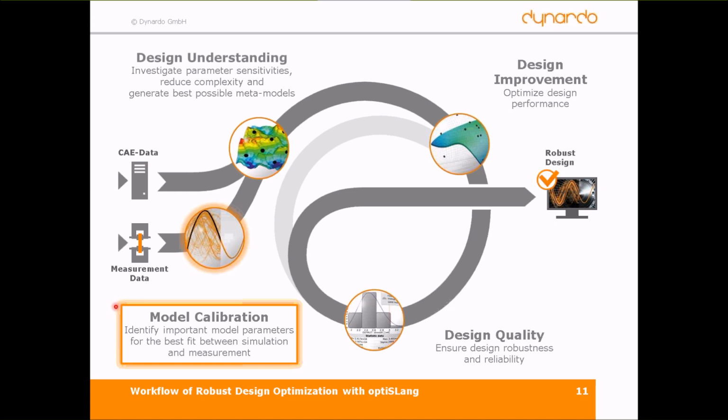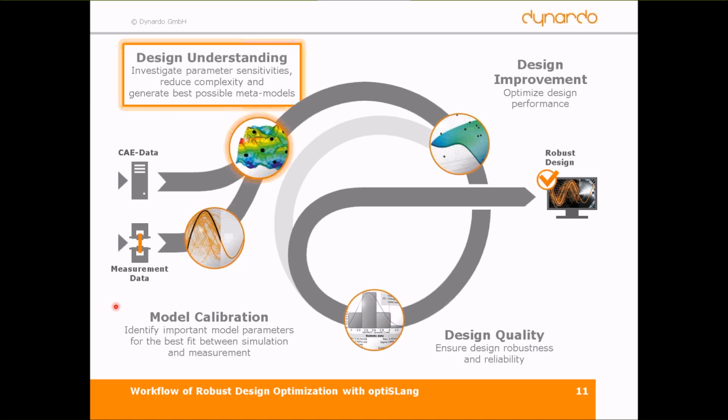One last word about the purposes of driving a design variation study, and particularly driving it with optiSLang. You can tweak the settings of a solver because you aim for the solver being capable of representing reality. As soon as the solver represents the real physics you're interested in, then you can use it, as long as the solver is not calibrated. Some solvers need calibration. Sometimes it's just a material constant, sometimes it's more state parameters of a solver. So that's a subclass of optimization. Generally, we have the three topics of sensitivity study, optimization, and robustness evaluation.